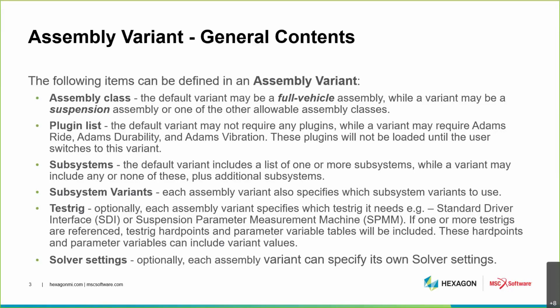And the reason I say or not is because we also implemented something called on-demand test rigs around the same time that we implemented variants, so that if the test rig is not stored with a particular assembly, it will be pulled in on demand based on the type of event that you are simulating in the current versions of Adams Car. Finally, solver settings, if they are specified, can be saved with an assembly.